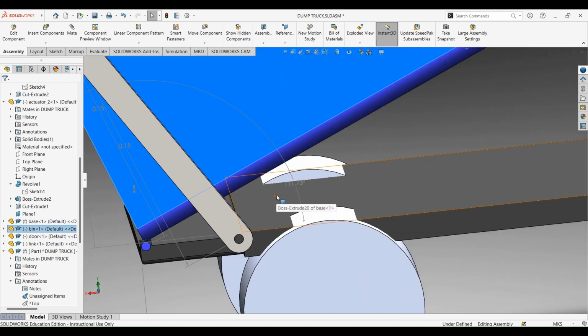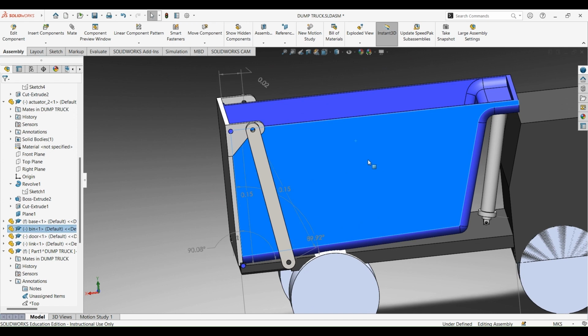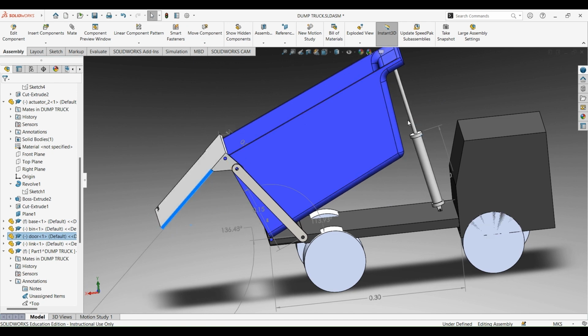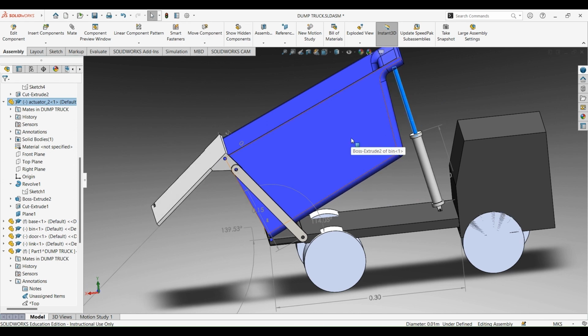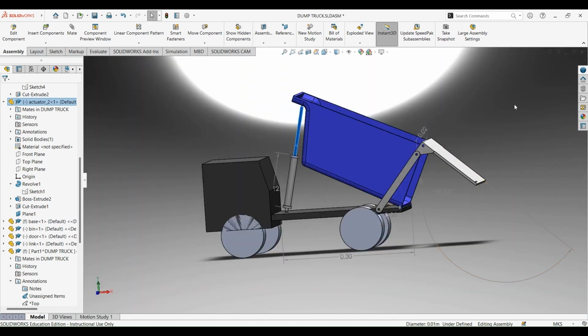This angle θ1 represents the tilt and this angle θ2 between the horizontal and the door is an indication of the opening angle. Their difference gives us the angle by which the door opens respective to the truck. In the fully closed position, both these angles are 90 degrees. In the maximum open position, θ1 is around 114 degrees while θ2 is 42 degrees, thus resulting in an opening of around 72 degrees. This is much more than what would have been possible with the same piston extension had the truck relied solely on gravity to keep the door open.